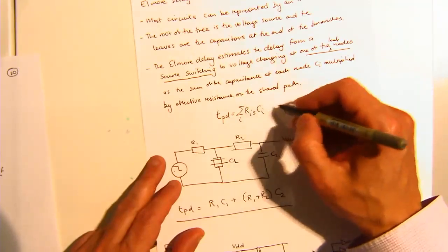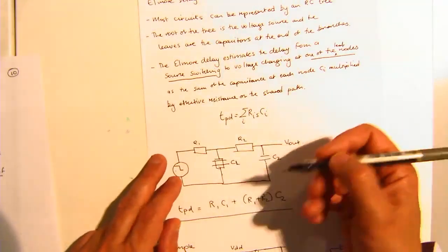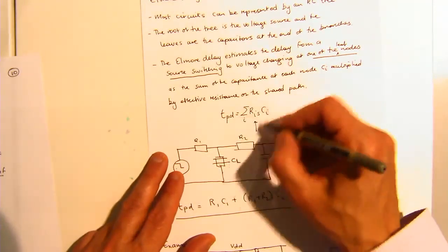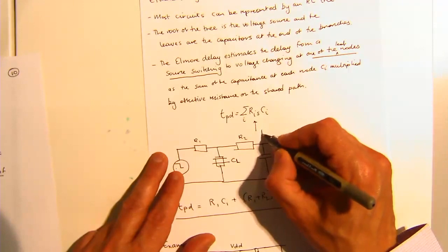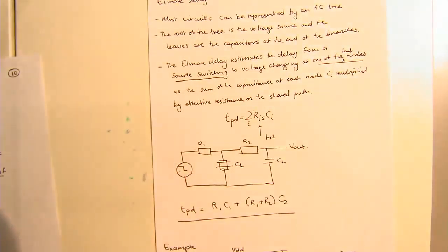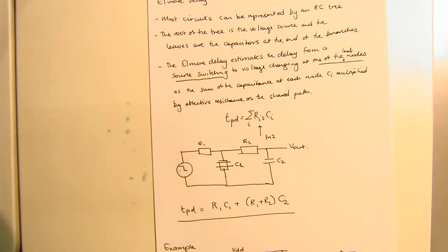put the log 2 there, but essentially, and we'll talk about this later on, you try to bring in, you increase the resistance by log 2, so therefore you don't have to have this log 2 factor running around. So usually what you try to do is make the resistance log 2 as large, so you say that my time delay is RC. Or you can actually have the real resistance and say real resistance times the capacitance times log 2.